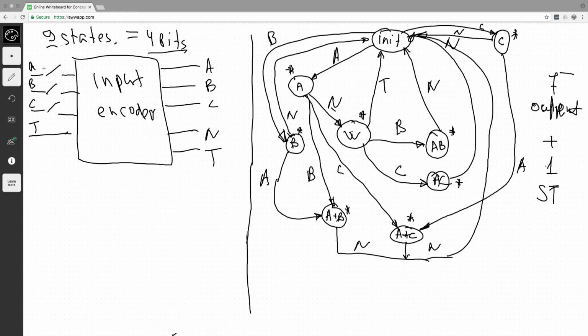From the perspective of implementation, the same time is an interval which is very short, and it is less than the time required for the transition from initialization to A. Let us just say that A has been pressed just a moment before B. So we go to A, and then we receive signal B, and we come here. So it is not A and B at the same time, it is A followed by B, while A is pressed.